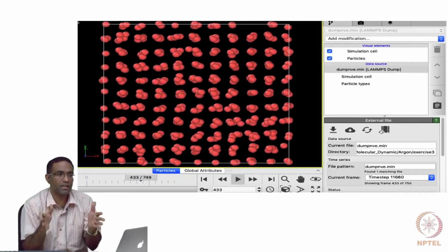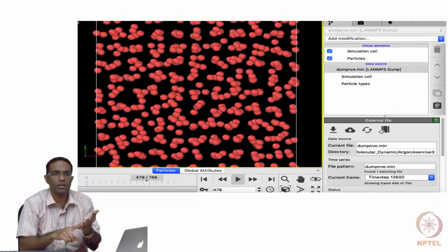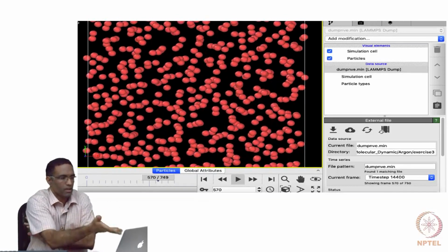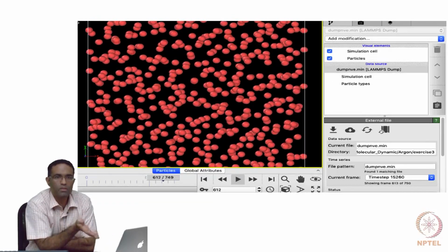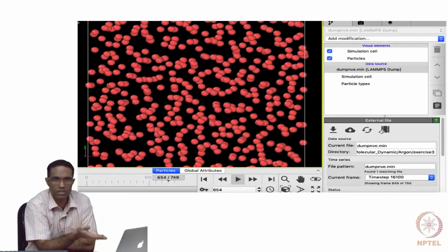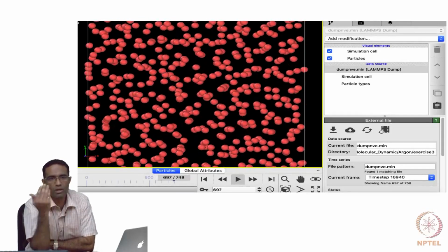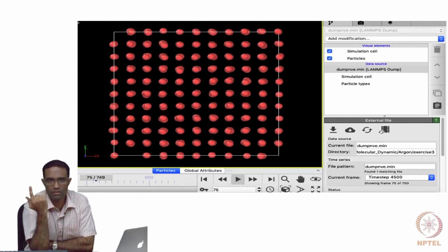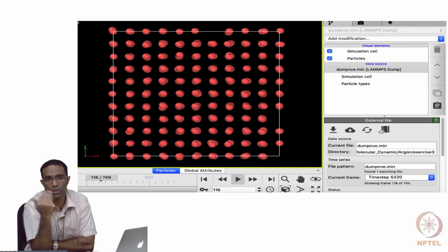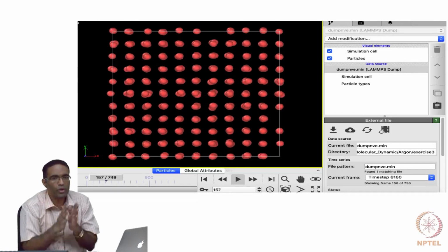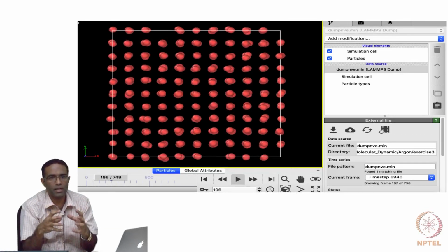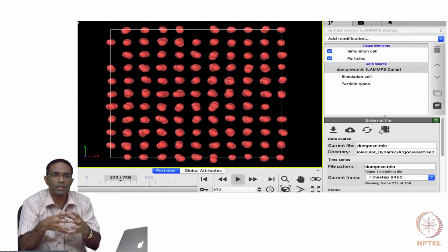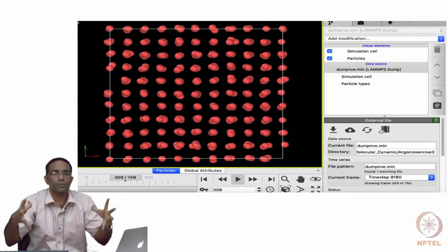Statistically mechanically, the pressure and the temperature of the ensemble is fixed. That is the macro state. But what you are trying to do in molecular dynamic simulation is you don't really know the positions and the velocities or the equilibrium configurations that the system must have at that pressure and temperature, right? You don't know how the velocities should evolve or how the position should evolve. So what you are doing is you are starting off with some arbitrary state and using this NPT fix to actually kind of train the system to reach that pressure and temperature.